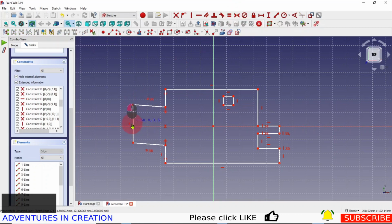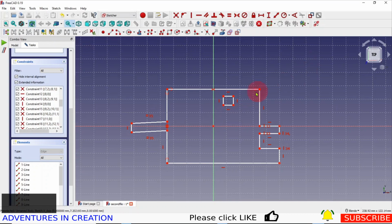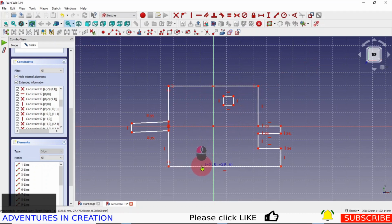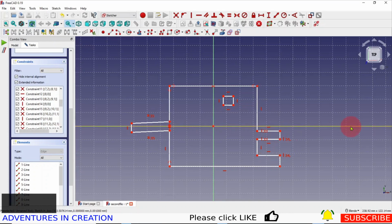And then I can move this down to somewhere close. I have this symmetrical and I have this part symmetrical. I could make symmetry this way around that center line, so that might work. I'll do that and that. Click that point. Symmetry. So now I have a symmetrical box that is around this line. And we'll just move those down because they don't want to be up there. They're going to be down here somewhere, I do believe. And we have the shape constrained from a geometry standpoint.